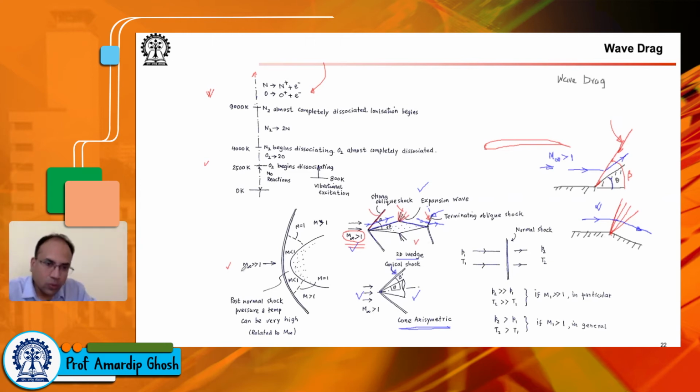Again, if you think of the space shuttle entering at very high Mach numbers, oftentimes you have... well, I should take back what I just said. It doesn't really depend on the Mach number. It depends on the combination of theta, beta, and Mach number. Sometimes we can have this thing which is known as a detached shock wave.